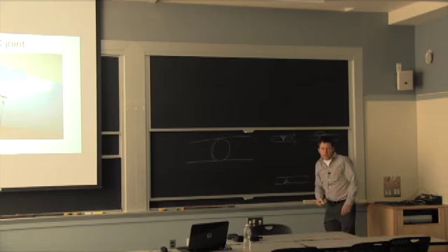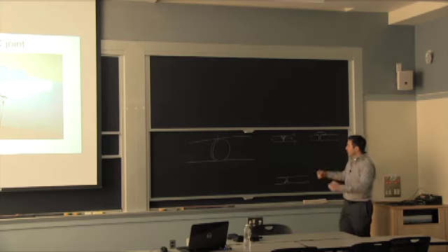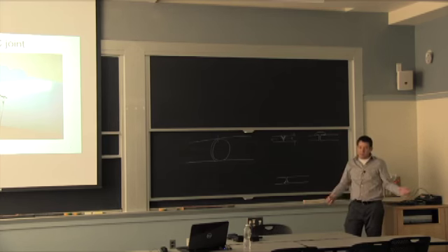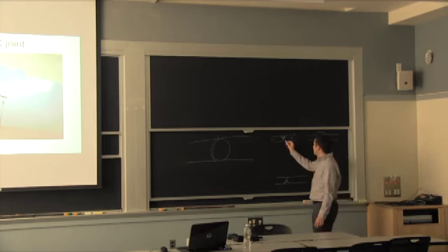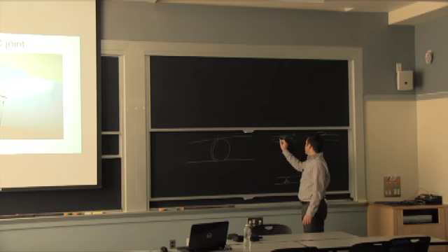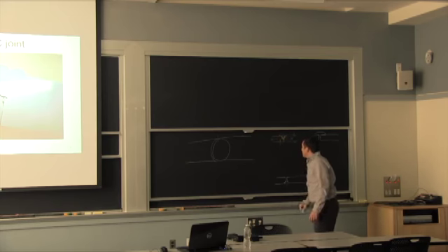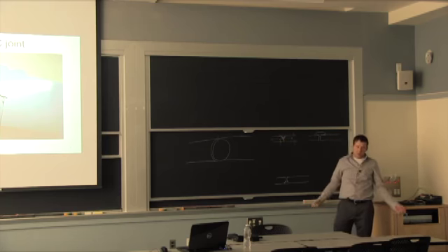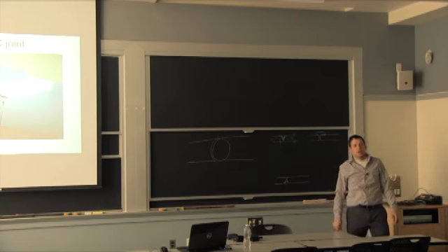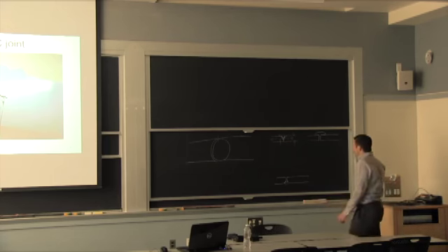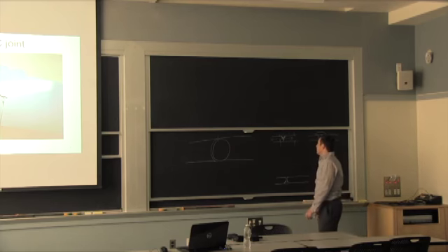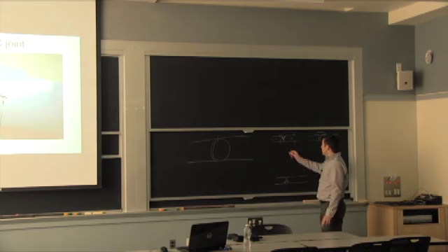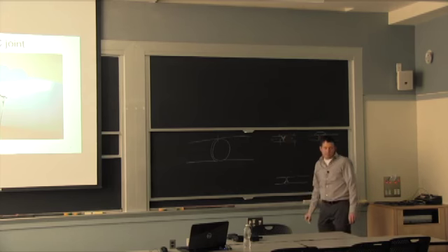You have a notch, and your strength in the axial direction is definitely less than half the strength of the full pipe, because you only have half of the throat. Sometimes we speak of throat as being the effective height that's welded. As long as this is not as big as the thickness, I'm going to have a reduced strength. I know that. I just don't know exactly how much. And it will vary if it's an overload or fatigue, and it will vary depending on the material. But the idea here is they should have done a deeper notch.